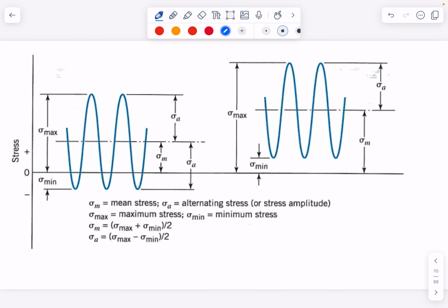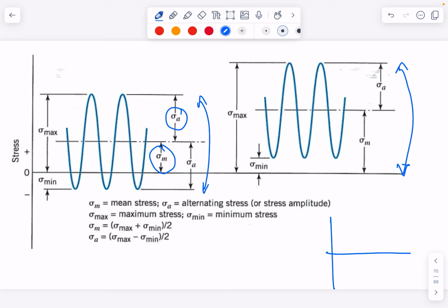So when we're looking at cyclic loads, I guess the important thing here is the mean and the amplitude of the cyclic stress. It doesn't need to be always one side. It doesn't always need to be all tension or all compression. It can straddle. So you can have a case where you have a zero mean stress and it's fully fluctuating around that zero point, through to a case where you've got a very high preload and all of your amplitude is way up there. So you've got a sigma M and then a little tiny sigma A on top.